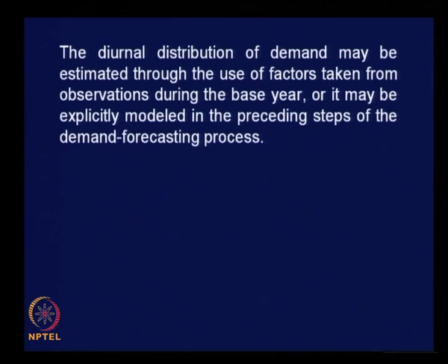After base year process is over, you are going to use these 4 models to do the same exercise for the horizon year condition, right, and your interest is to know the horizon year peak situations also. The simple question is, what percentage of the 24-hour traffic will constitute morning peak, is not it. It is a reasonable question.